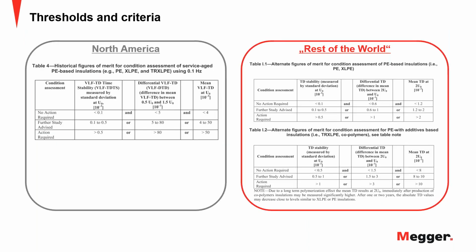And here's pretty much the standard, or the guide, that is governing that. So in the IEEE 400.2, you can find these things. Now, what you're actually measuring there is pretty much the resistive losses versus the capacitive losses in the cable, right?